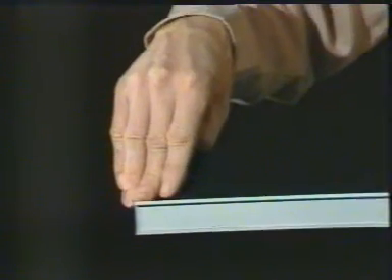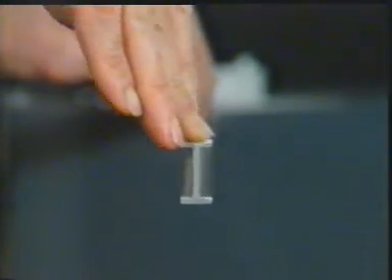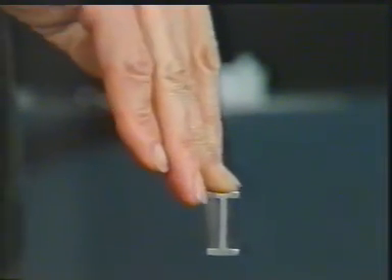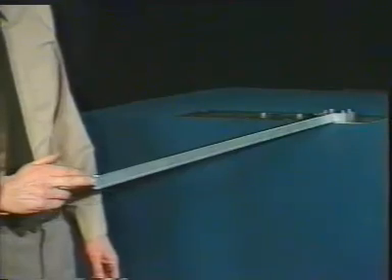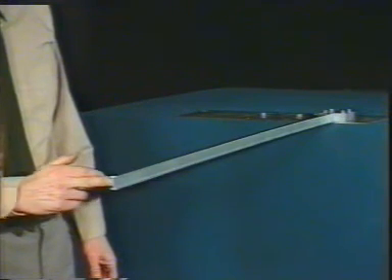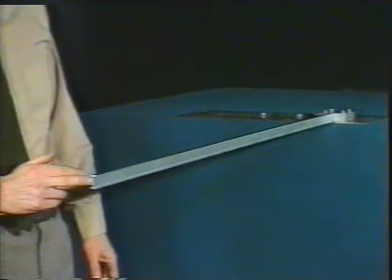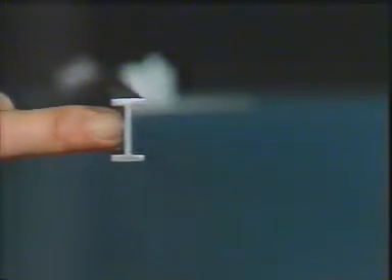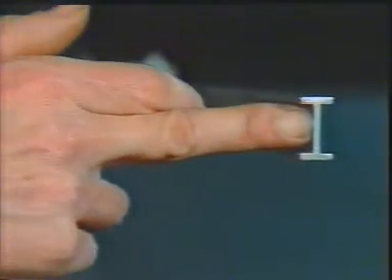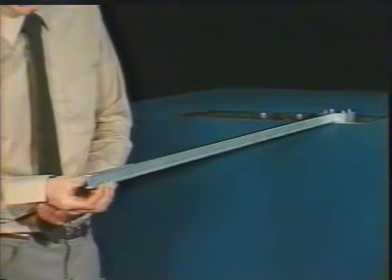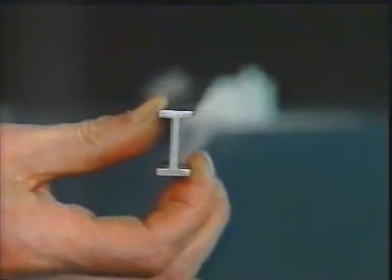Firstly, observe the response to a vertical load applied at the free end and through the centroid of the cross-section. The end moves downwards, with flexure occurring about the major axis. If a horizontal load is applied at the free end, through the centroid of the cross-section, the cantilever responds by moving laterally. When the free end is subjected to a pure torque, the section twists without any translation of the centroid.